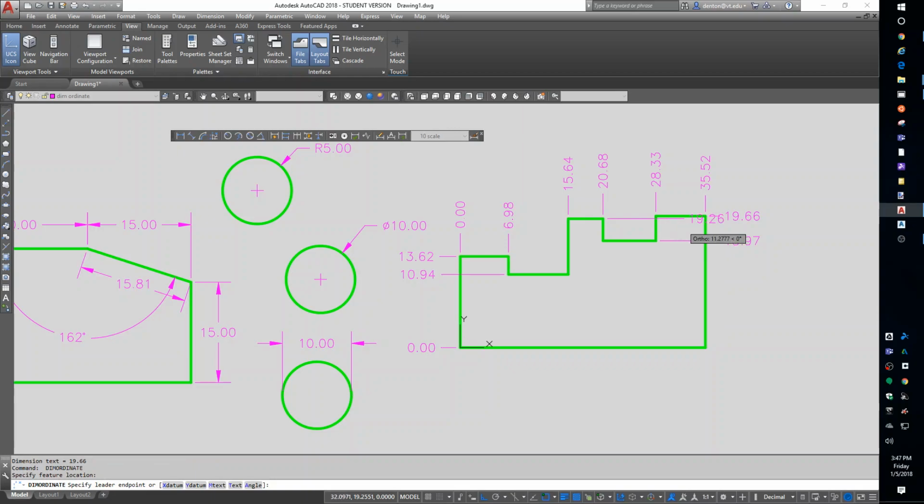Now, if you have things that are close to lining up but don't quite, you can turn off your ortho to go crooked, and it will bend the line. That way you can label things that are close to lining up but not interfere with the text. So that is called an ordinate. To put the 0, 0 back where it belongs, UCS, and an extra enter for world coordinate puts it back to where 0 is supposed to be.